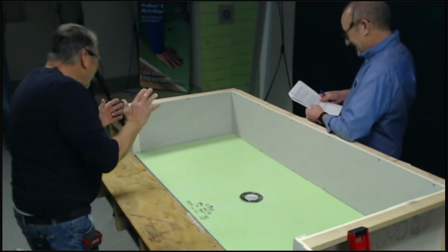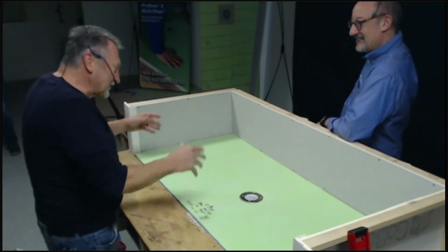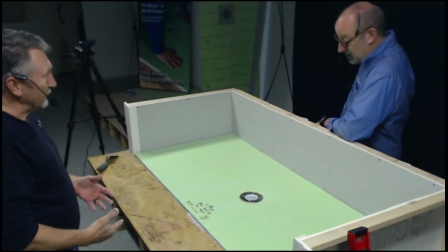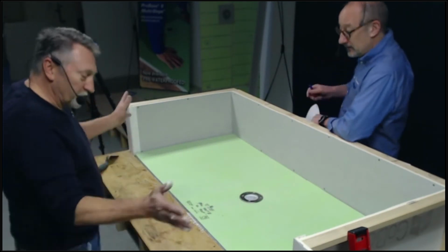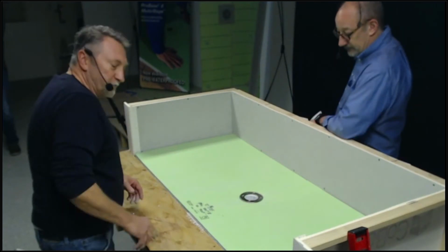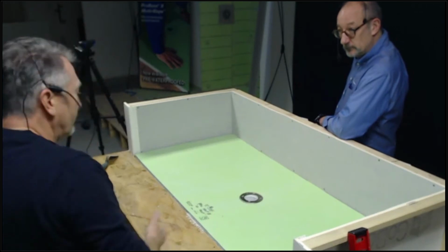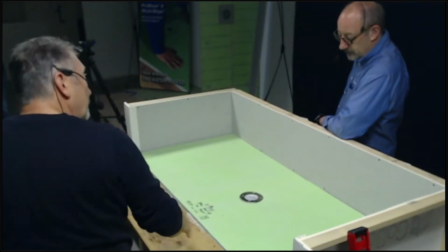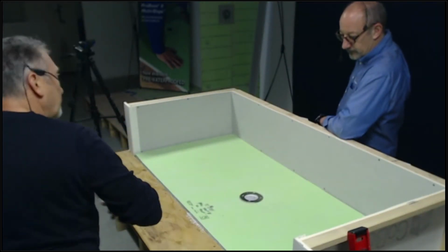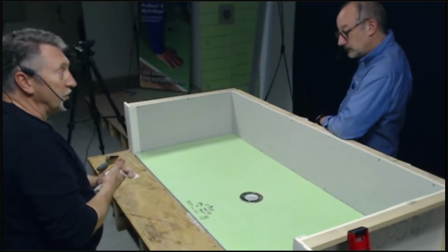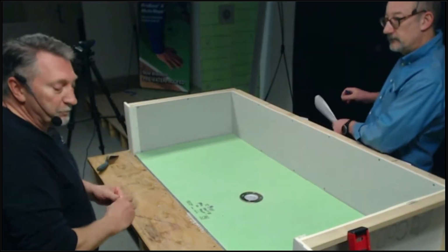Okay, so now the base is installed, waterproof, and everything's sloping to the drain. At this point, I only have about 3/8 of an inch to maybe 1/2 inch from the base to the dry space. In this case, you feather that out. You can build up your dry space with say a 1/2 inch backer board. Now you don't have a lot of buildup.